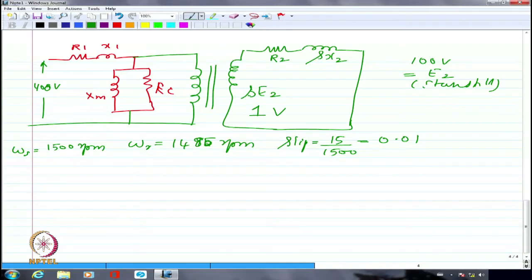Whatever is the minimum current that is needed, first of all, to develop that minimum torque, frictional torque, and also to establish the flux. Xm will require some current to establish the flux. So you will see that as the induction motor starts, the current falls very rapidly because of this particular reason.